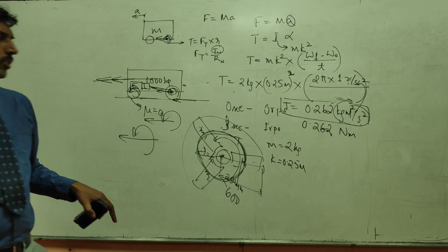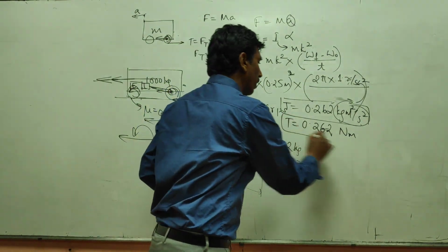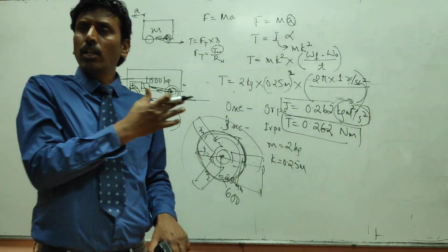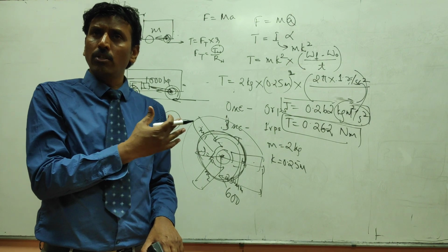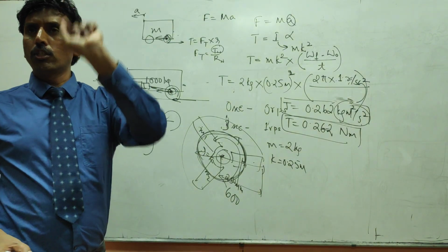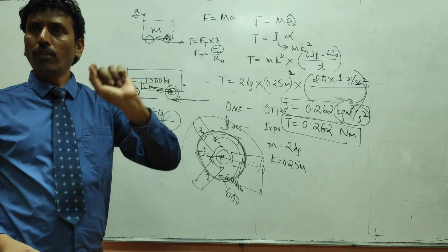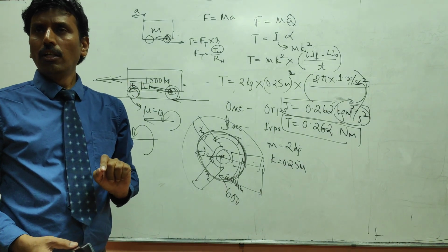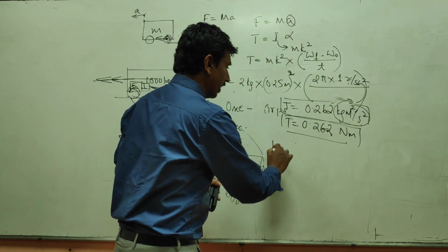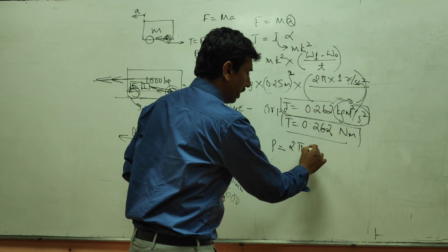Guys, you just got the torque, but I wanted power. You said 75 watts, no? Let us check whether our basic fundamental equations are at least close to that value. Suppose I put it to fifth speed, you said 75 watts of power that it consumed. Let us use the equation P is equal to 2 pi nT by 60.